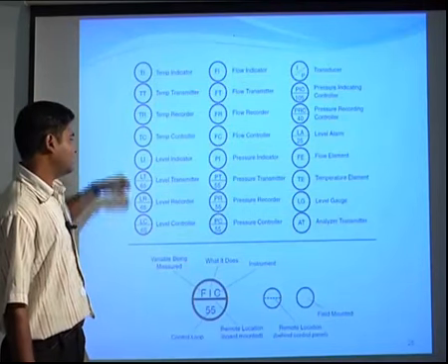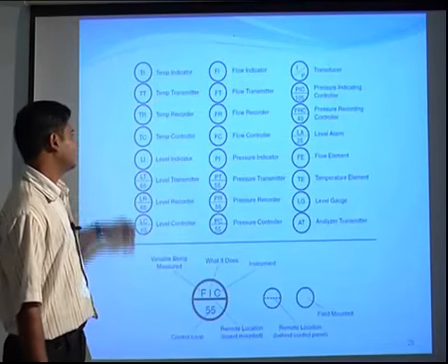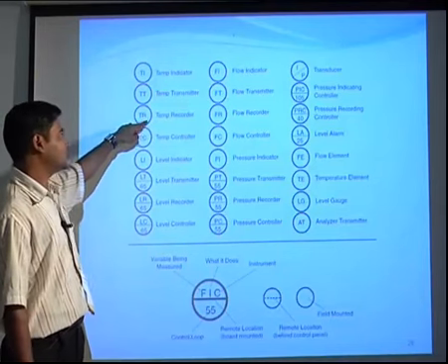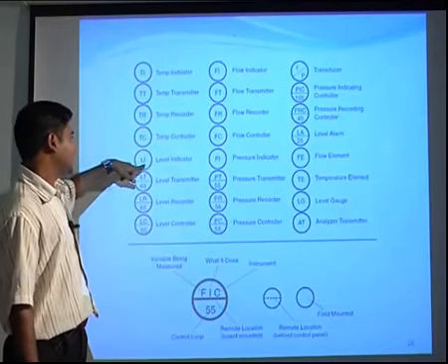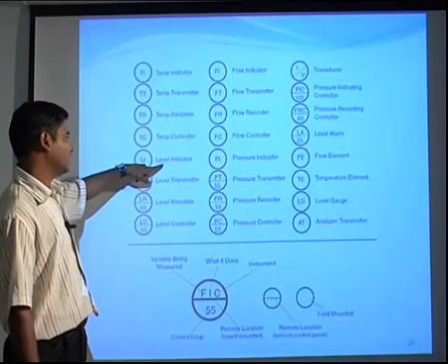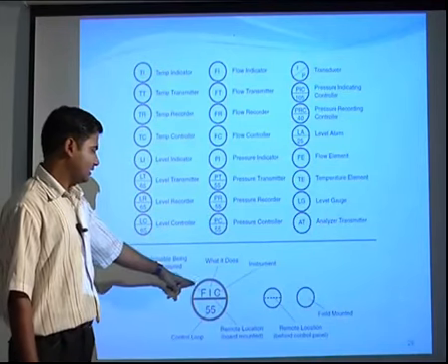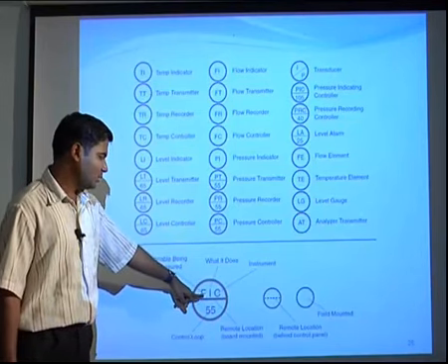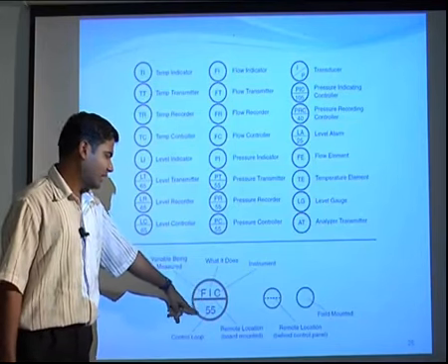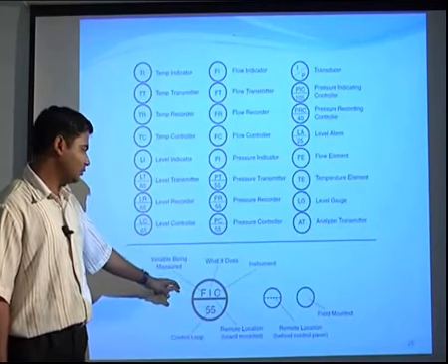Then there are different kinds of control systems. If you take the example TR, that represents temperature recorder. Then LI indicates the level, so level indicator. In a block or a circle, it may be two or three alphabets, and some numbers will be given. So how to read them?